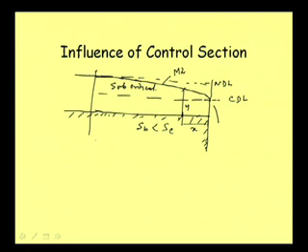One thing we can do is start from uniform flow and then start computing in this direction. We will compute till the flow is just higher than critical depth, because at critical depth this cannot be computed, because our slope becomes infinite and that is not computable. So just above the critical depth we can compute and we can stop. That way we will get the total length.